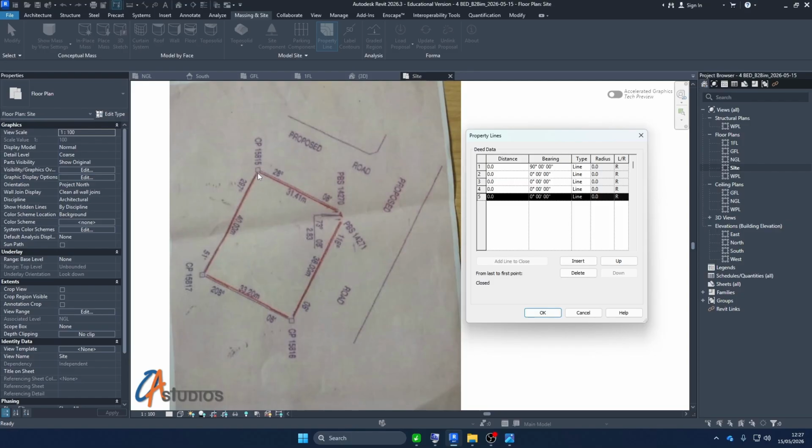Now we would start with the smallest bearing and go clockwise till we get to the highest one. So the distance here is 31.41. Now remember, we set our distance from the beginning to meters. So when we type this in, we should put it in meters, not in millimeters, because this is distance. So for this we'll do 31.41.